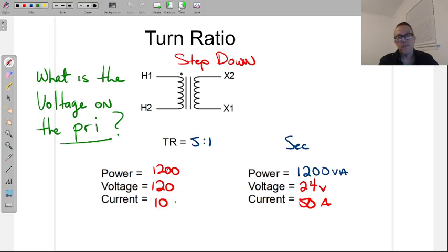So now here's the other important part of the transformer. One is, again, when you go to order this transformer, you're going to connect it to the load. So you're worried about the load's wattage, because that's how you're going to buy the transformer. So for example, this transformer would be a 1.2 kVA transformer. I mean, you don't have to buy it so close.